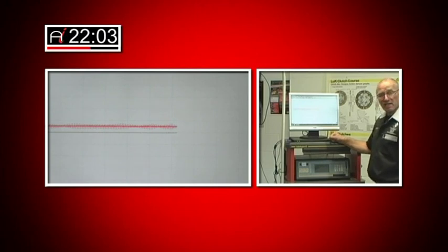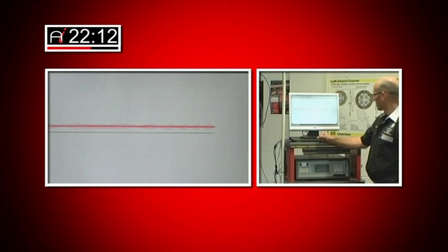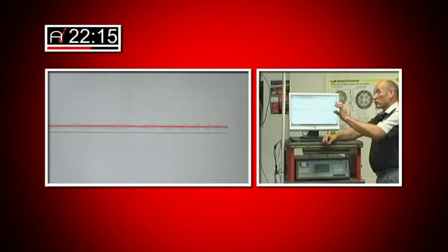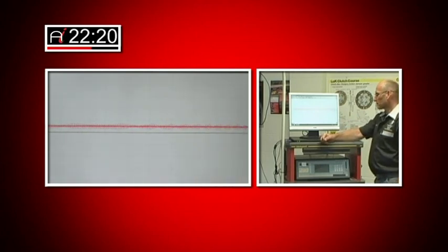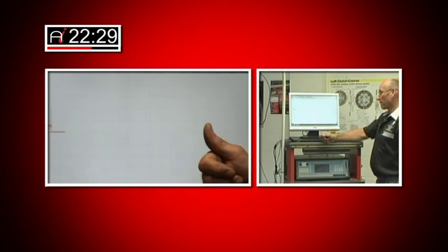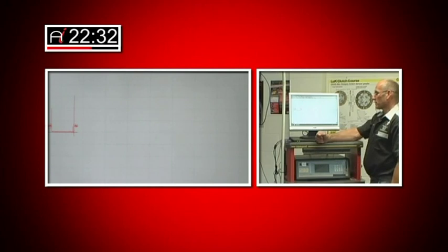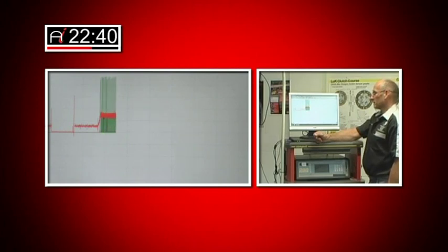As I say, we're going to do a whole series of tests, not just to see what the voltage is, but also how quickly the voltage changes in respect of cranking and starting and full throttle. So if you can get ready, if you could turn the key off to begin with, please. That's the system parked up. Key on, static, do not crank. There's your half volt. Crank and start, do not rev up. Full throttle.